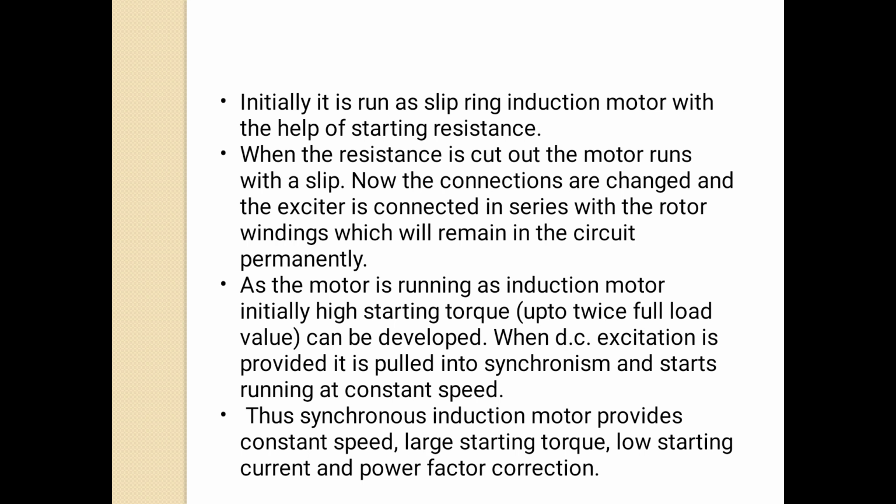The DC excitation is fixed in space and does not shift when the rotor carries alternating current. The fixed rotor poles get magnetically locked with the rotating magnetic field produced by the three-phase stator winding carrying alternating currents, and the rotor runs at constant speed.